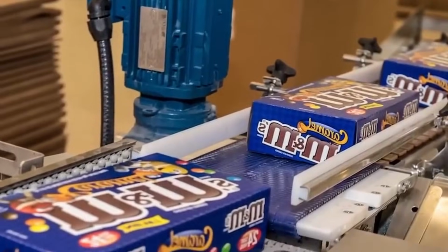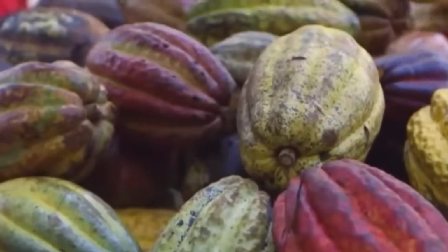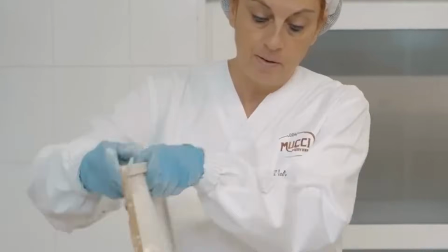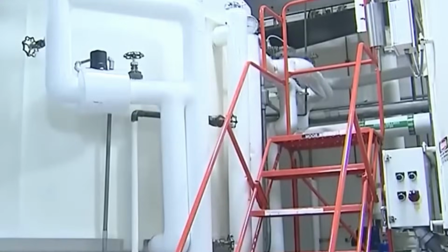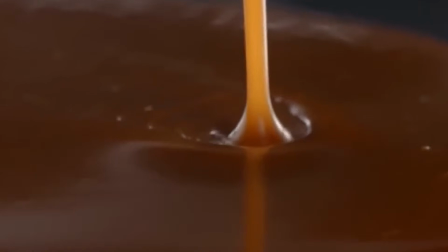A multi-tiered vibratory grading system separates any units that deviate from size specifications. Grading is followed by weight sorting, using high-speed check weighers capable of scanning up to 300 units per minute. Acceptable candies fall within a defined weight range. Over- and underweight items are automatically rejected and logged by defect code.